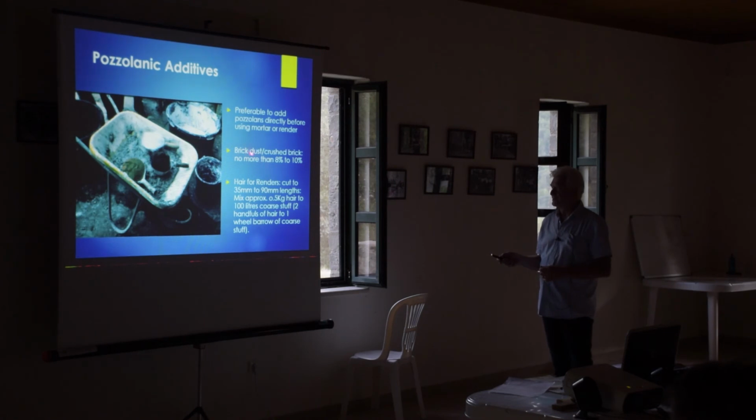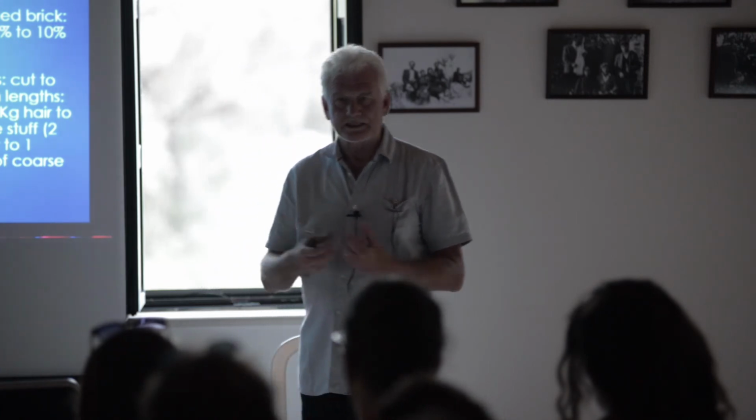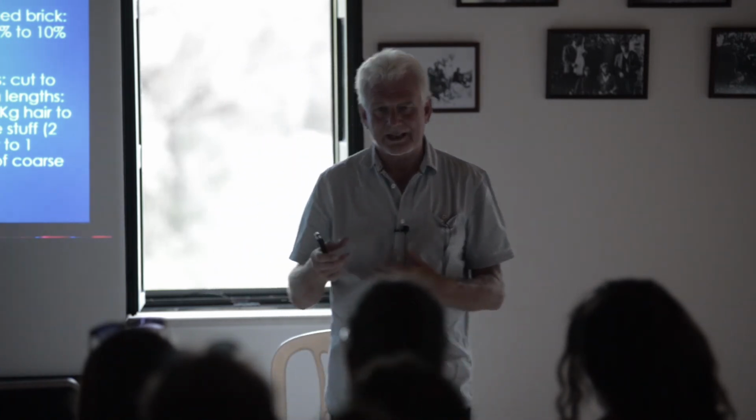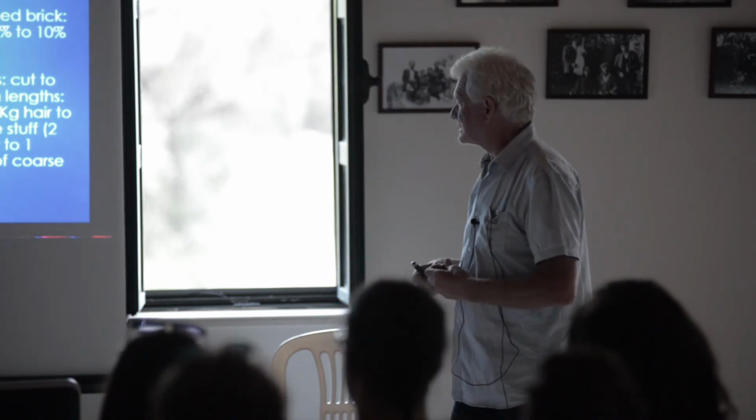If you're using brick dust or crushed brick, you shouldn't really use more than 8 to 10%, because it'll make the mortar too hard, and the reaction between the lime and the brick will be too excessive.